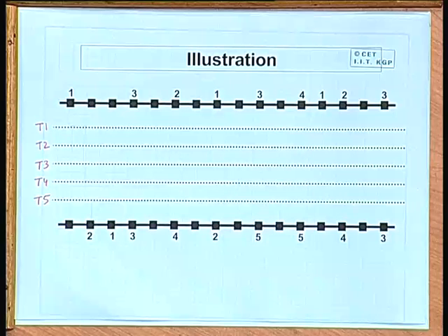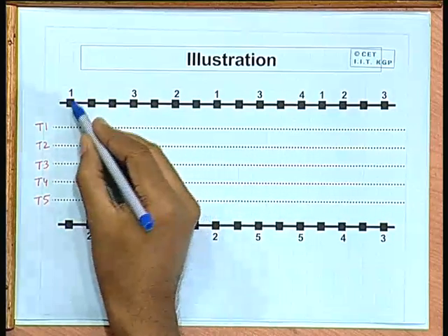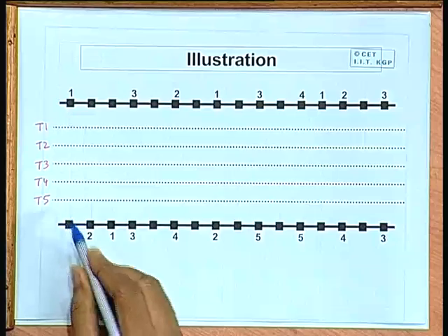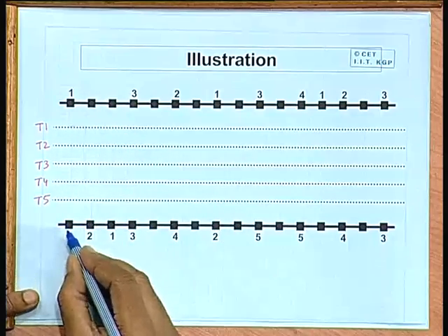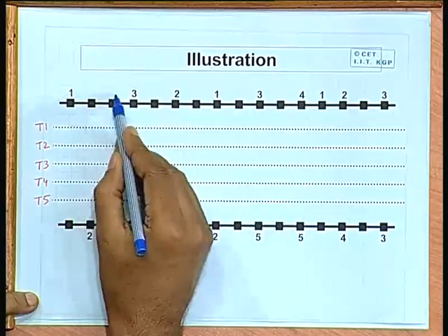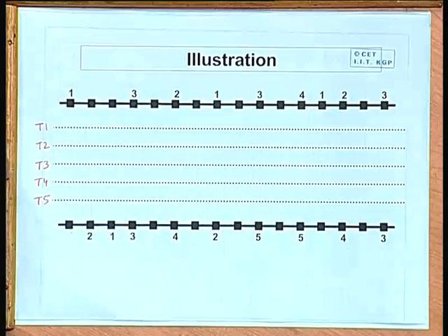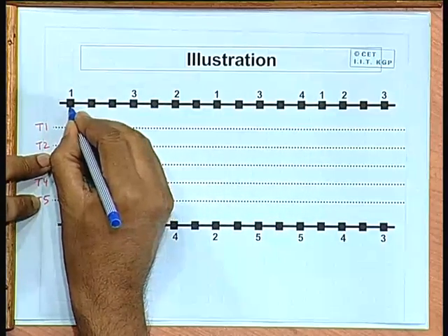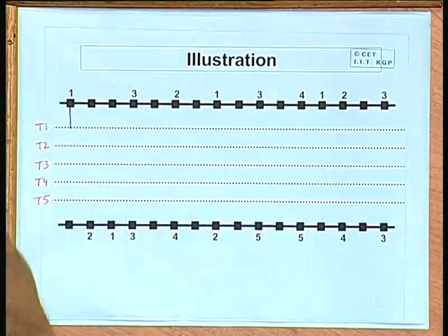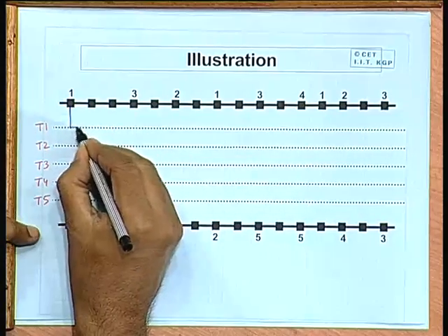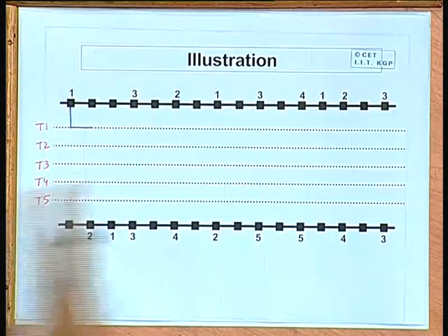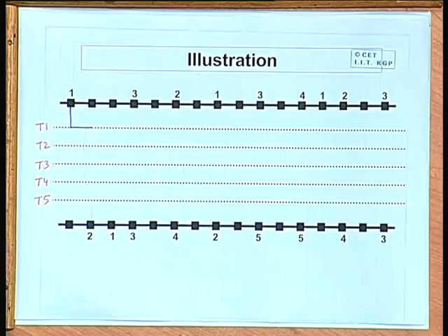Well, in the first column you have only net number 1. I have not shown the zeros; the unnumbered terminals are the zeros, or no connections. So in the first column you have only 1. So you use the first track to extend net number 1.